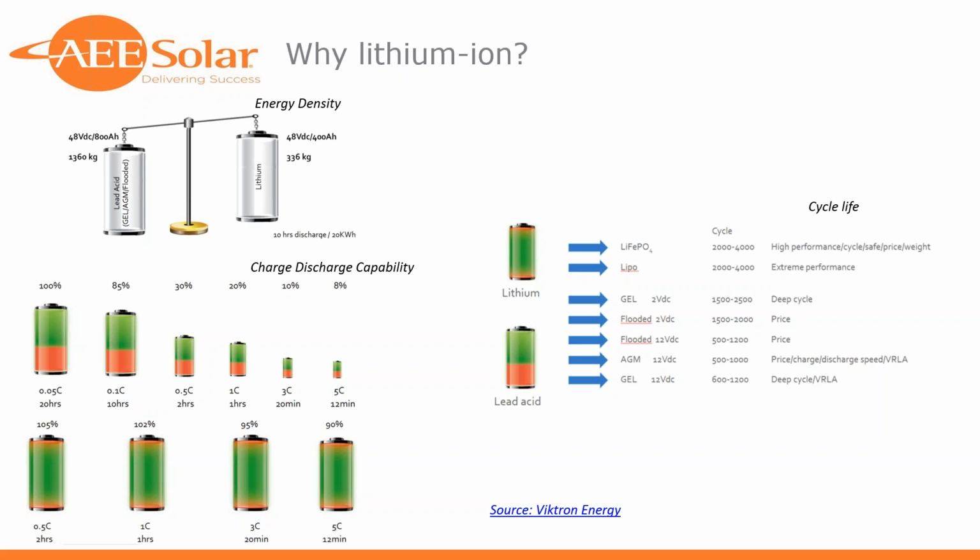As most of you know, on the lead acid front, if you're intending that battery bank to do regular cycling, you're really not going to want to plan around a depth of discharge more than 50%. If you're using it strictly as backup, with a set use case, and it's not going to cycle more than a couple times a year, you can plan around an 80% depth of discharge. Even still, 50 or 80 versus 95 plus, it's clear you can get more usable energy out of the same nameplate capacity in a lithium ion battery, in addition to it weighing less and taking up less space.